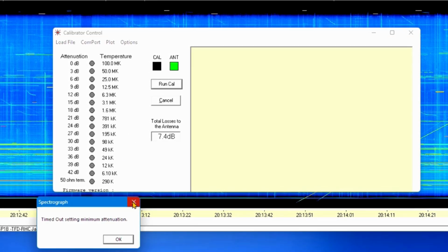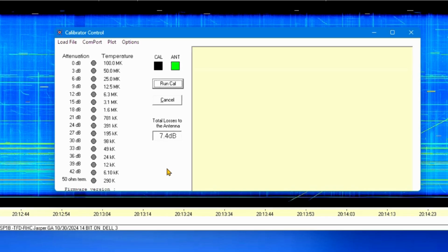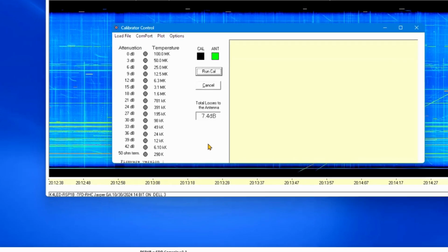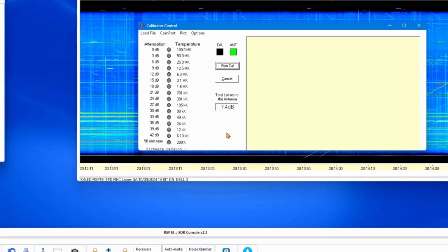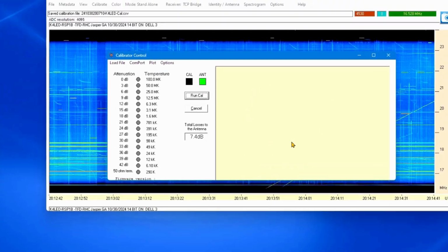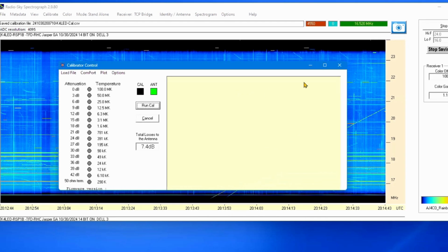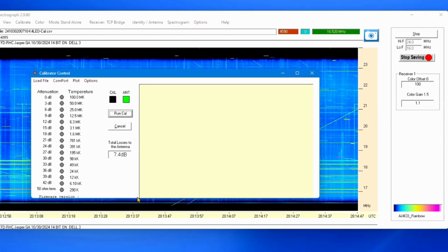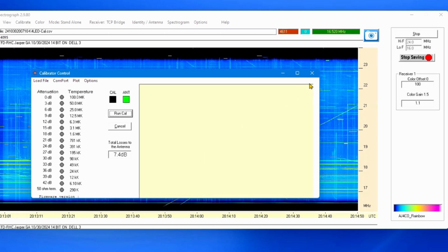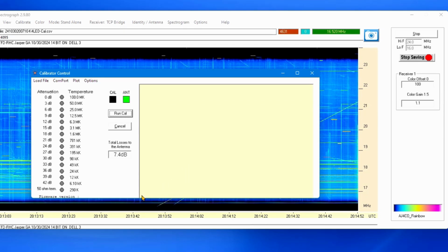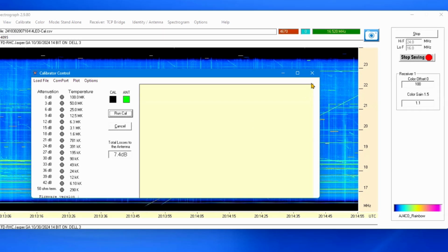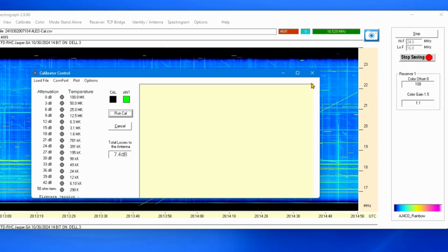The first step in the calibration process is adjusting for a proper dynamic range using the built-in RSS calibration plot graph. The goal is to get a plot line from the RSS calibration plot's bottom left corner to the top right corner. The dynamic range adjustments set the weakest and strongest signals to their proper dB settings for viewing in Radio Sky Spectrograph.